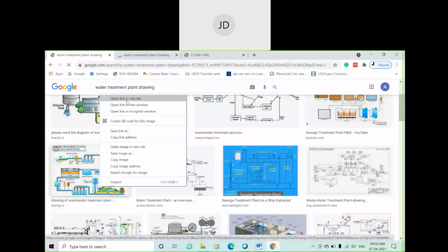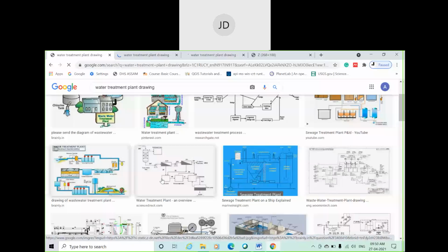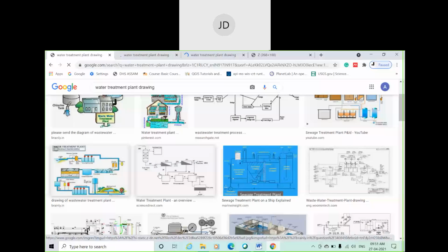Okay, so after screen you have to provide aeration. So what does aeration do? Aeration means it actually passes air into water. In aeration, air is allowed to pass through the water. And what is the advantage of that? Air means we are introducing oxygen into the water. And you also know that oxygen is very important. Why is oxygen very important? Because it does oxidation of organic matter.